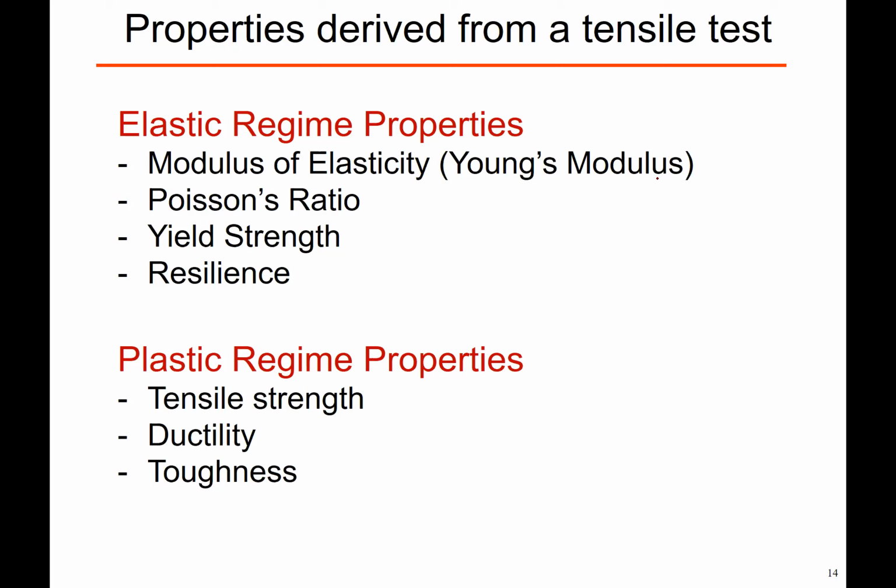So in thinking about, if you're the designer of, say, the F-150, and you think about designing a chassis that can absorb a lot of impact, right? You don't actually want your material to just fracture upon impact, right? You want that body to actually absorb a lot of the energy so that it deflects it off of the passengers that are inside the car itself, right? You need to pick materials that have high toughness, but also high ductility, right? So these are the things you want to think about for these particular cases.